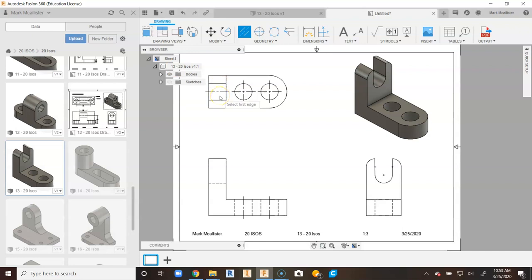Since this surface right here is, let's say, kind of a half pipe for a skateboarder, if you will, like in this area it's a half circle, I would put a center line up here. We're going to right click and we're going to say OK. What we'll do is we're going to go in and do our hole dimensions and our radial dimensions first. So we will come up and click on dimension, and we're going to go ahead and do the outside radius of this arc first, and that is a radius of 2.